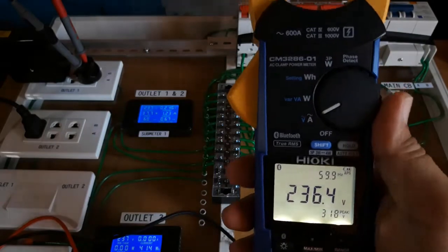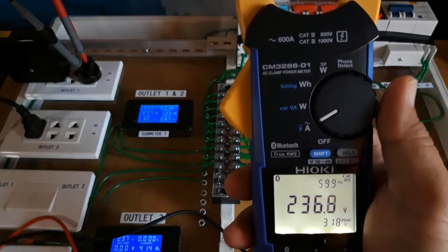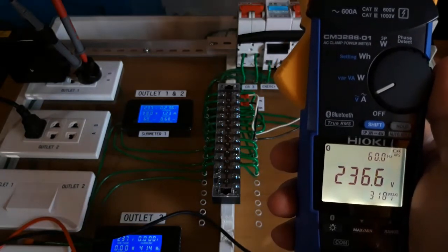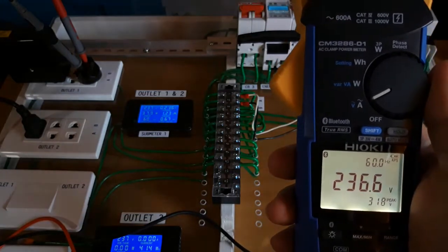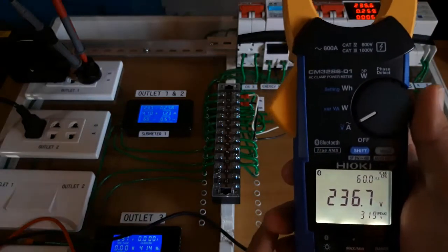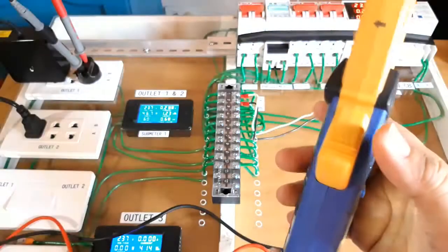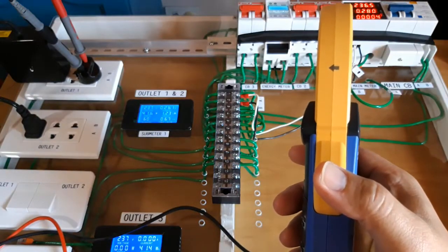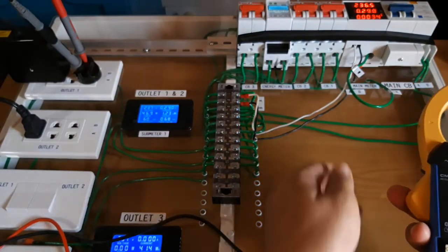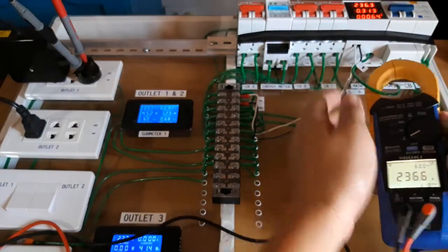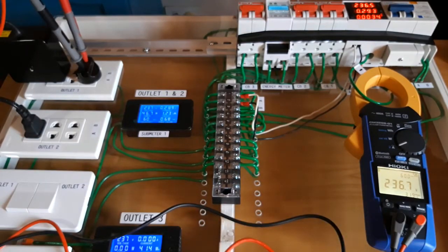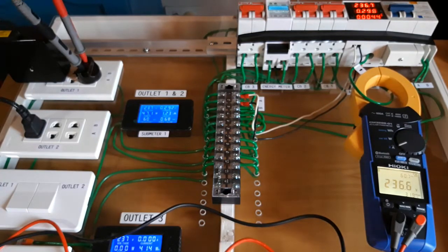However, when we're measuring power or energy, for example power, which is an integration of 3 different values at the same time, voltage, current, and power factor, the instrument's internal microprocessor requires a certain fixed reference point. In other words, the conductor being clamped, this one, and the red probe must be the same line.